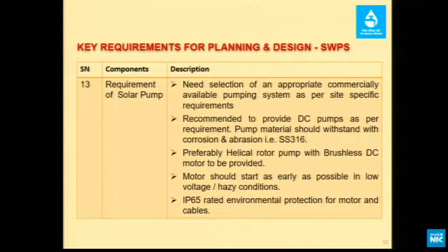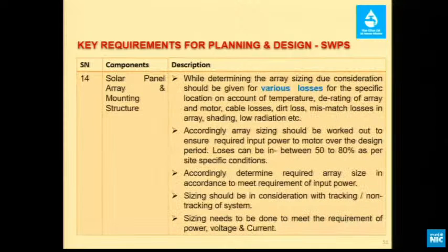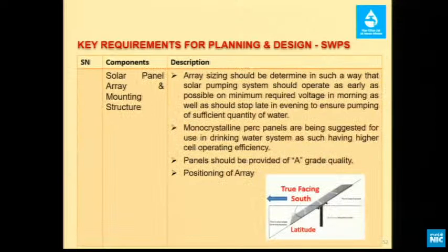And next, most preferably, I suggest a DC pump, because DC pumps have higher efficiency in comparison to AC ones, and I am getting the DC power from my panels, so my cost optimization will be there. And again, for the panel sizing, site-specific requirements are needed much more here, right?